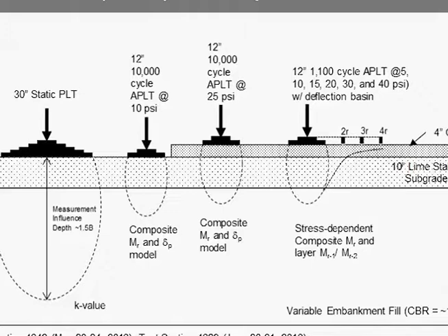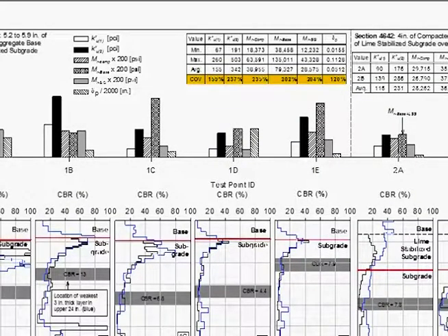We had a lime stabilized layer, this fat clay subgrade. We had a CA6 virgin crushed limestone material. We had different stress levels, measured deflection basins, so we could calculate all the necessary parameters. And on this project, what we found out is that there's just an awful lot of variability in these mechanistic values. And these were actually research sections. They were built to support research pavement sections.